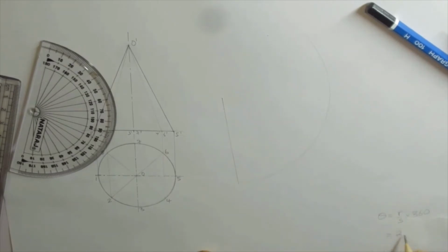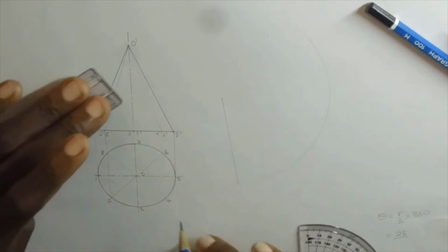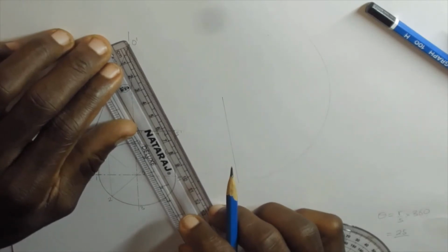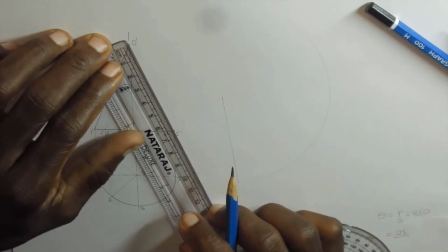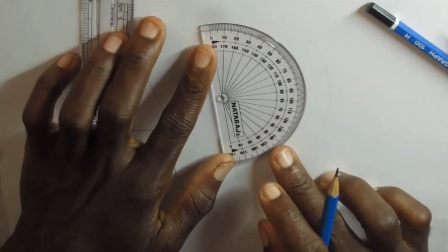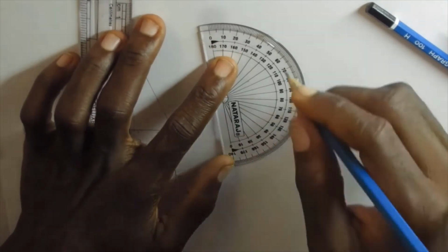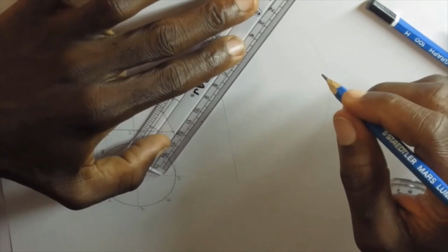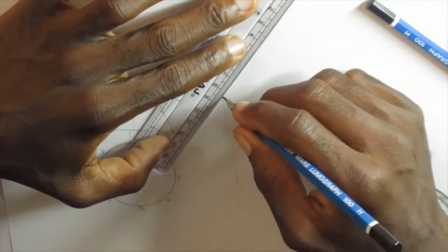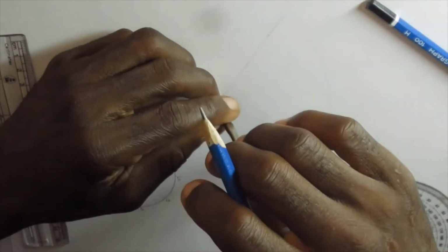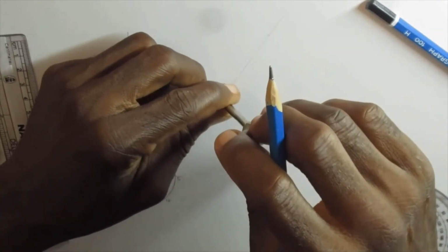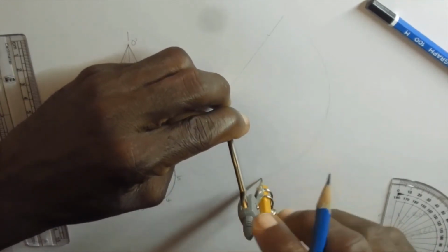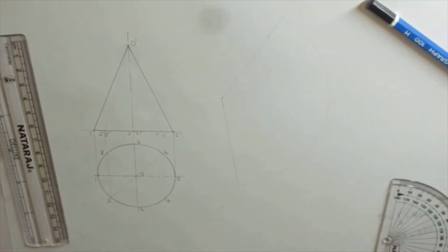And the formula we use for that is theta equals r divided by s times 360. Okay, and r, which is the radius of the base circle, is 25. And then the s will be the true length of the slanted side of the cone. So the true length, we measure that distance, and that will give us 65. So you can put that into the equation, and when you have the angle, which is 138.5. Okay, so we use that,